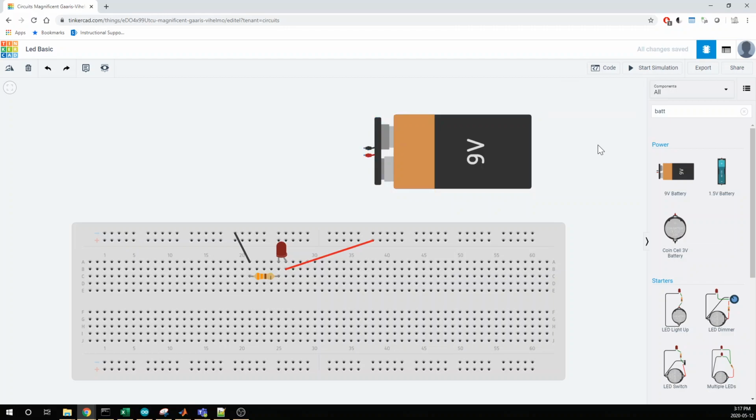And you'll notice that Tinkercad actually follows the same convention for power and ground that I did. So we have red, which is your positive, and negative, which is black. So I'm going to make a connection from here, the negative, to my negative rail. I know that there are some tricks. For example, you should always connect your negatives first and that sort of thing.